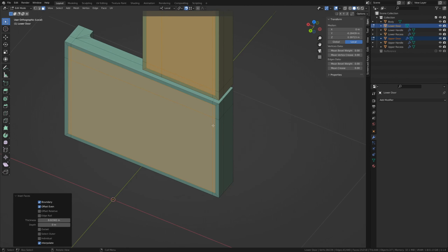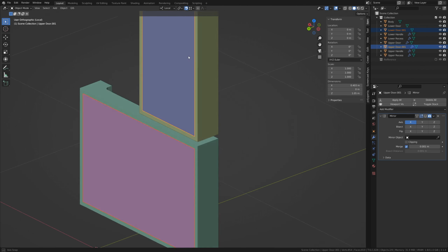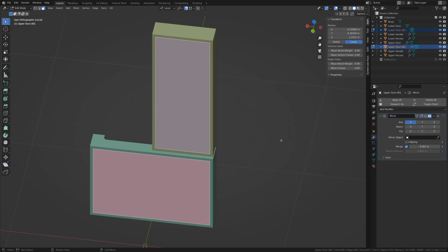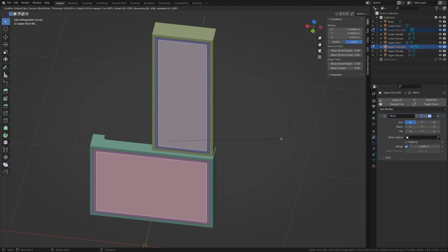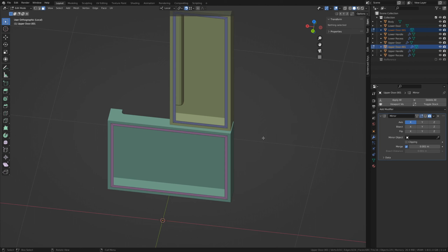So let's separate those right now. Let's go into edit mode on both of those. And now we don't need all this extra geometry on these, so let's get rid of it. Control Delete or Control X will dissolve without destroying your mesh. Select both faces and inset again. We're not going to need this center face on either of these, so delete faces, select all faces, and we